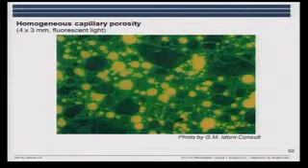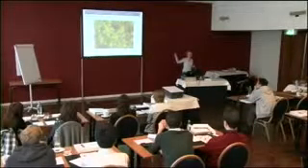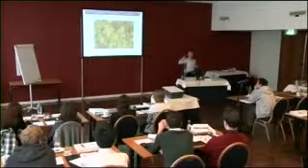Then the next is, now we're moving up. You saw some of these slides yesterday? Or not slides, but sections. A thin section. So this is an epoxy impregnated thin section. It's 20 microns thick. It's important that it has the same, or a constant, thickness because we use it for assessing the capillary porosity by the intensity of the green color.